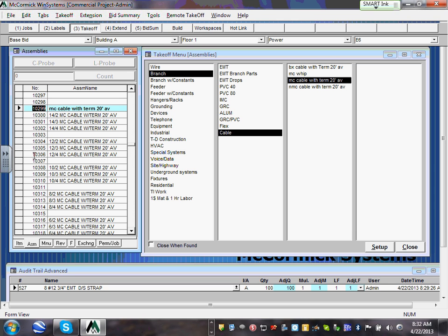Everybody knows why 12.4? When you have a receptacle here, guys, if you circuit them right, you should use a multi-wire branch circuit. Now, Darren, a multi-wire branch circuit needs how many conductors? 4. Phase A, phase B, phase C, and a neutral. So when you take an MC cable with 4, you can pick 3 circuits out of that. So I can pick up circuit 1, circuit 2, and circuit 3. They have to be the multi-wire branch circuit, if you circuit them right.